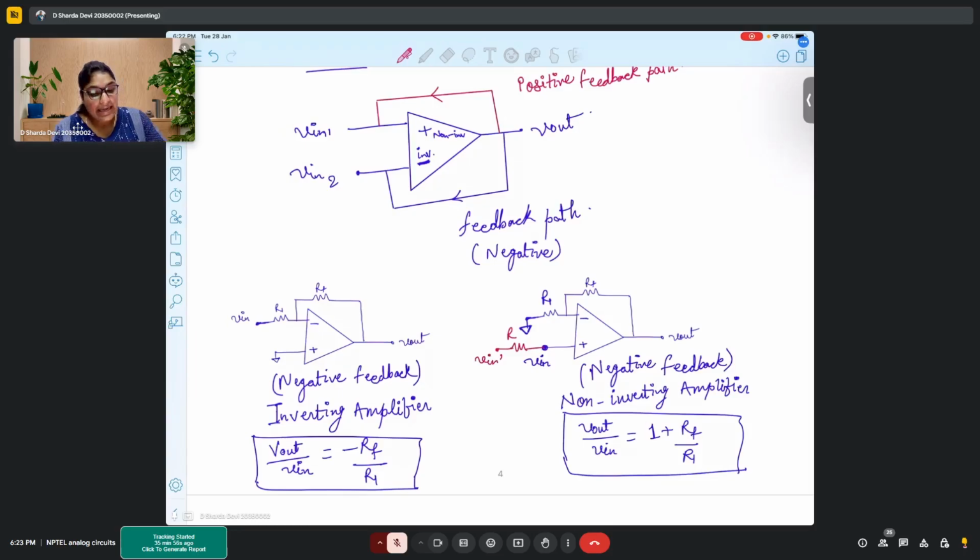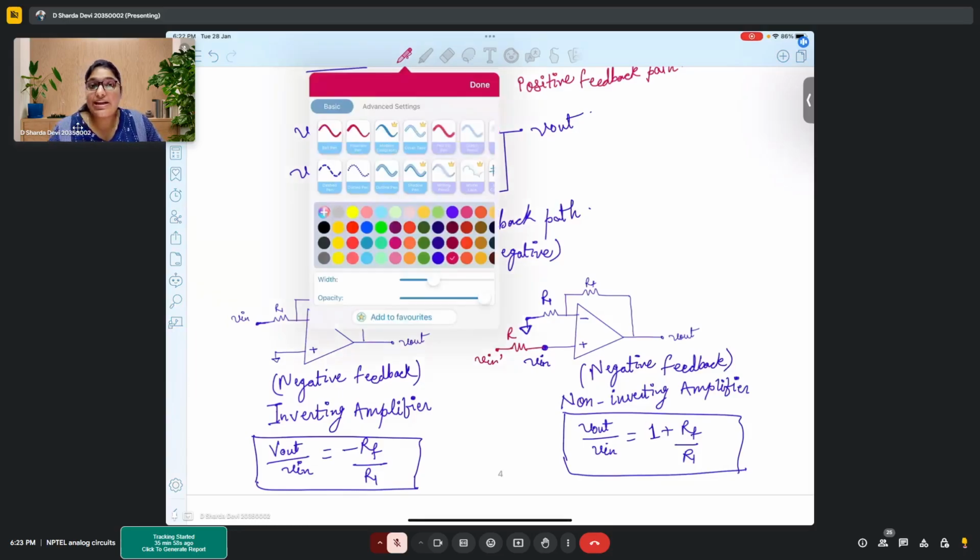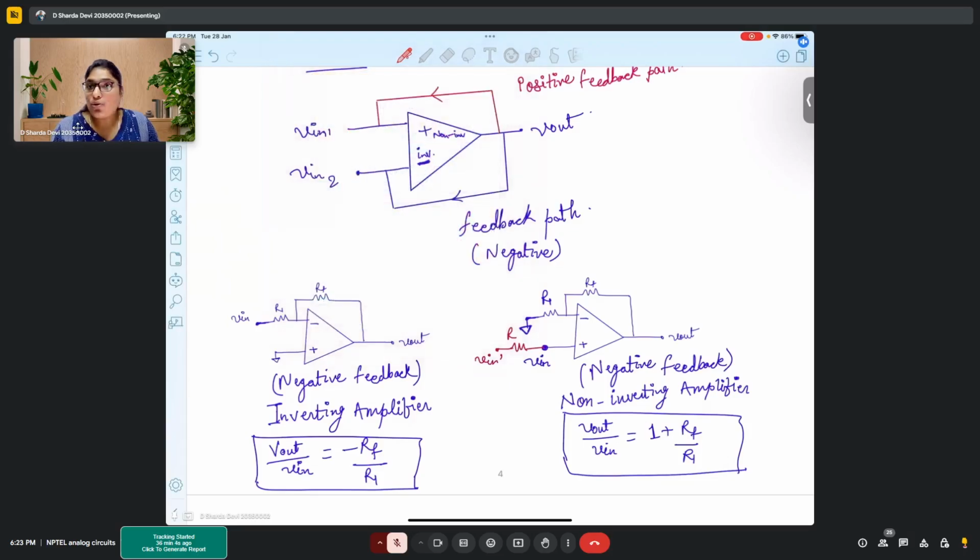Okay, there are few things that you need to remember, everyone. Please pay attention. In your op-amp, when you look at the input terminals, and if you try to inject current through your input terminals, the current will always be zero. Like current cannot go through your input. So you have to keep this in mind. So here I is zero.